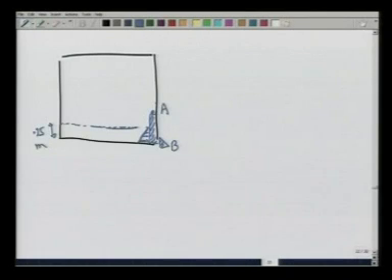So, in this lecture we have used the concept of centroid and the first moment and the area of load versus distance curves to get some formulae to see where effectively a given force or distributed force acts, and then applied it in situations where a beam was loaded or when a sheet was submerged in water.